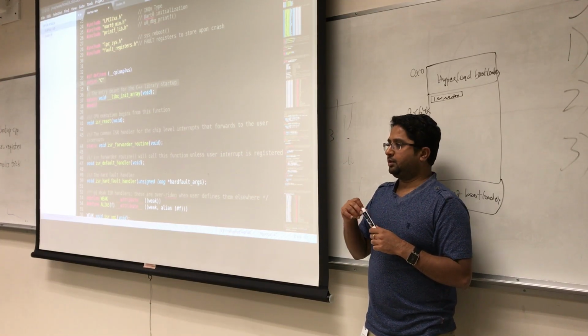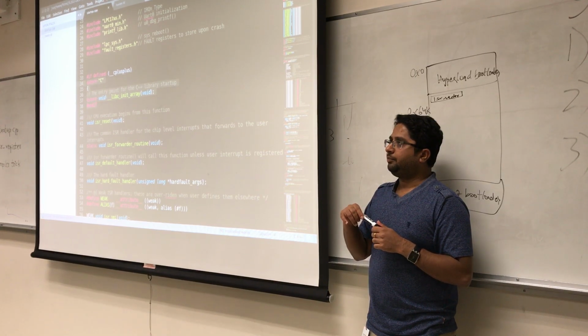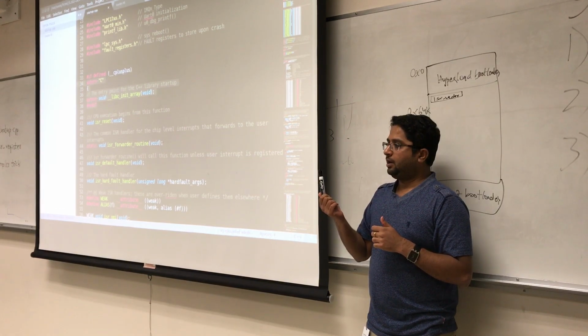You can write it outside the task, where you have this interrupt handler function, and then look at the status of the pin, do a certain function when the interrupt happens, and then reset the status so that the interrupt is clear.